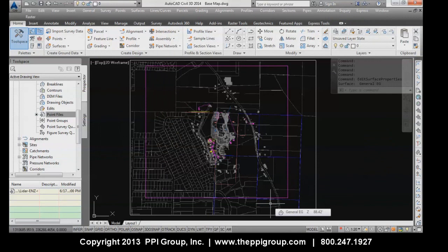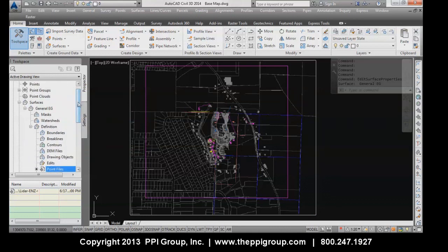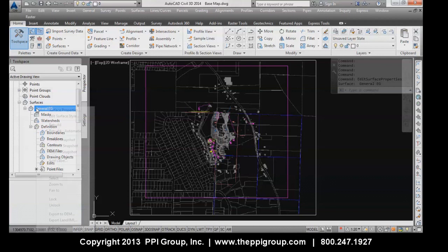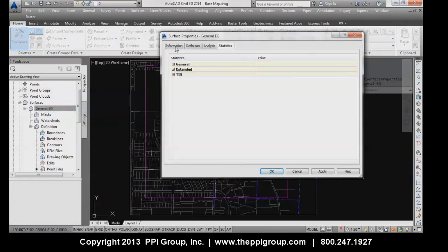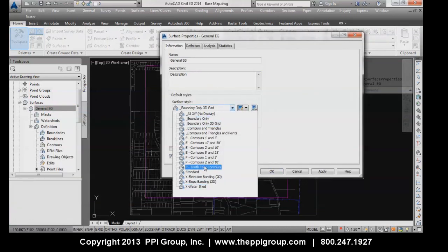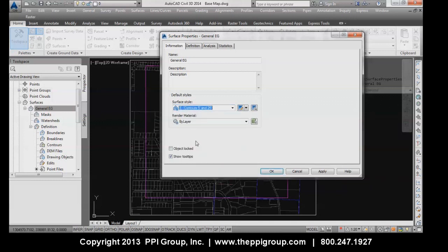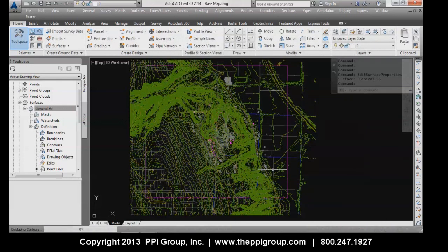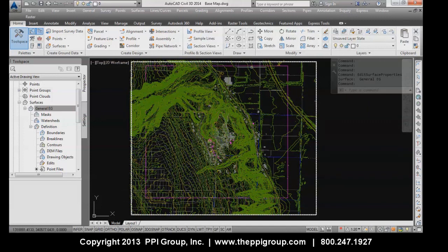Now, two last things we can do to this to continually bring this information down. I'm going to change out the style a bit here so we can see a bit more what's happening. I've already tested this. Sometimes you'll want to check it on your own just to make sure it's not too dense. If you have too much relief in the land, obviously you'd have way too many contours, which could again be very taxing. I've already looked at this, and 5 and 25 is going to work for me. And you can see how the extreme boundary is surpassing this outer edge here.